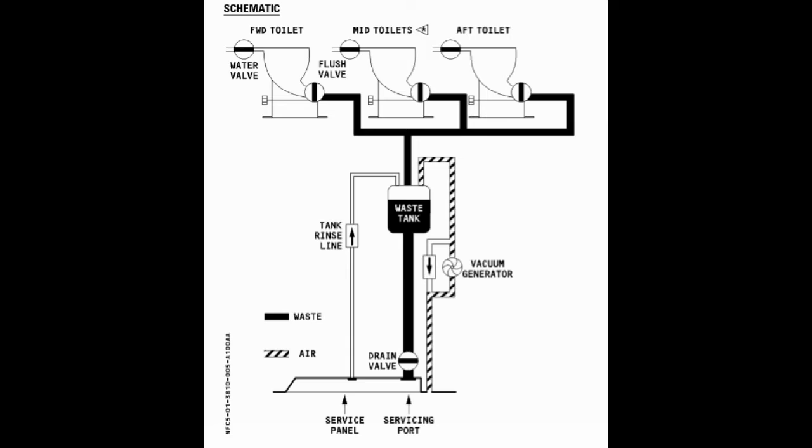When you press the flush switch in the toilet, the rinse water valve will open for approximately a second, discharging disinfecting water into the toilet bowl. After this valve is closed, the flush valve or drainage valve will electrically motor open, exposing the contents of the toilet bowl to negative pressure.